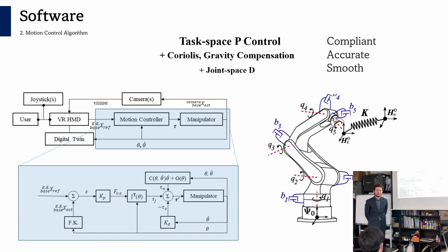For example, if motor 2, for Q2 and B2, is moving at 1 radian per second, it shows some kind of performance. But if the frequency range changes to 5 radians per second, then B2 will give us different characteristics. So if you select B1, B2, B3, B4 as a function of the frequencies, then you can tune all the frequency ranges to match all the dynamics.